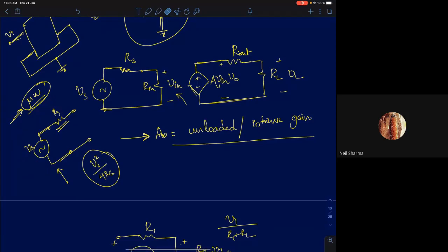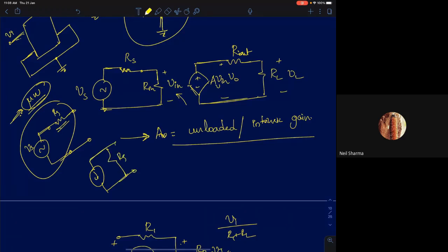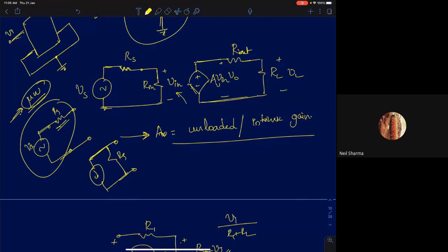Similarly, by Thevenin-Norton equivalence, by an equivalent Norton representation, I can convert a voltage source and resistance in series to a current source and resistor in parallel. So one of you asked, why do we have to put a resistor in parallel, when in the case of a voltage source we put it in series? One way is to look at it directly from the Norton to Thevenin equivalent.